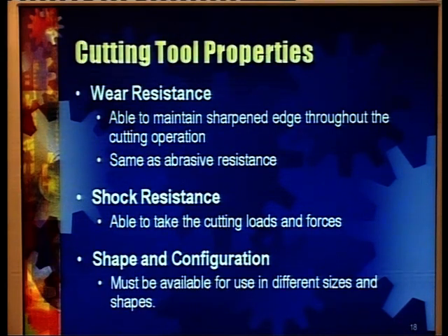I am saying this because in some cases, such as a single point cutting tool which we use in a lathe machine, even if the tool breaks, we can regrind it, in case of course of HSS tools. But in case a milling cutter breaks, and one or two edges break off, then we will need to replace the whole cutter and the cost will be much more.